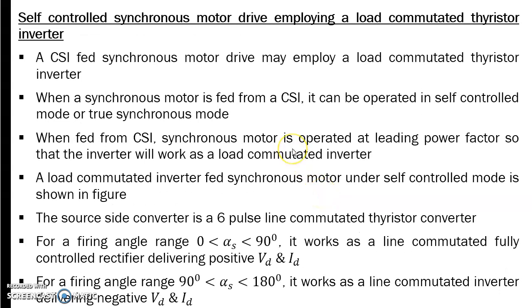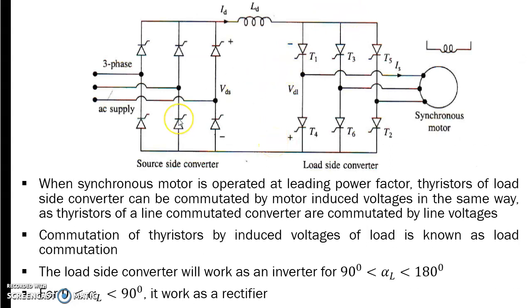And let's discuss one of the major synchronous motor drives. The name is self-controlled synchronous motor drive employing a load commutated thyristor inverter. As the name implies, it is self-controlled. It can also operate in the open loop mode. So this is the circuit diagram for the particular drive.